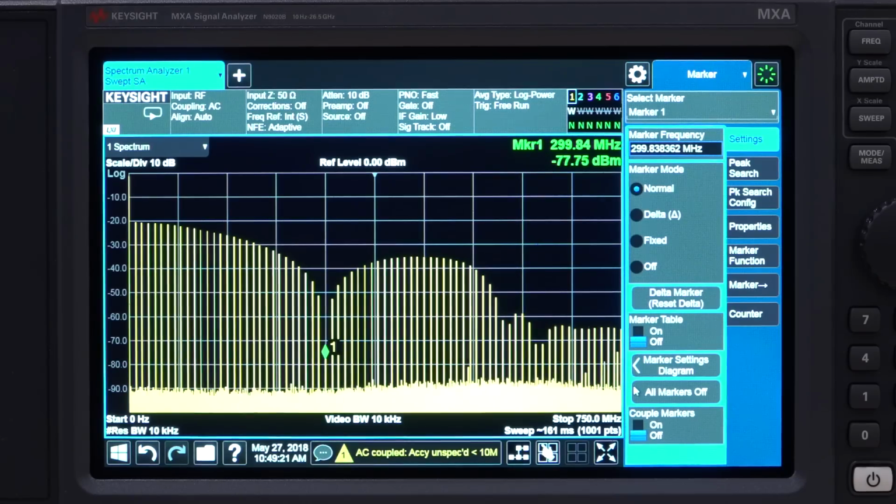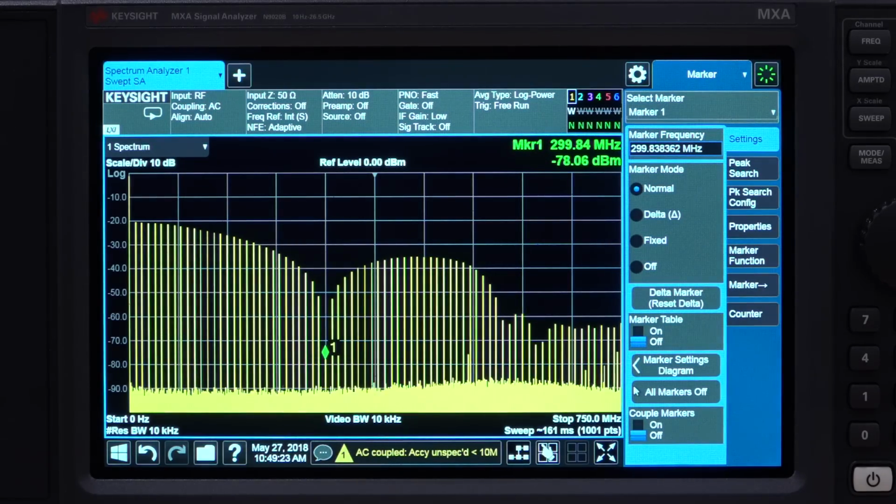And there it is, and we get exactly what we would expect. We get a train of impulses which are 10 megahertz spaced, and there's going to be a null associated with the limitation of the pulse width. We have about 3.3 nanoseconds here, which translates to roughly 300 megahertz, which is exactly what we're getting. And we can see the sinc function shape superimposed on our train of impulses. So this represents the bandwidth limitation of the output of this instrument from the point of view of creating pulses.